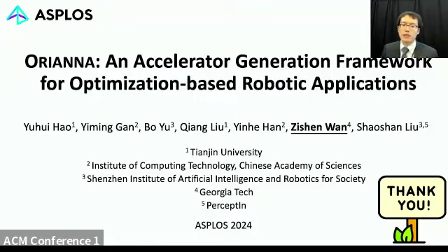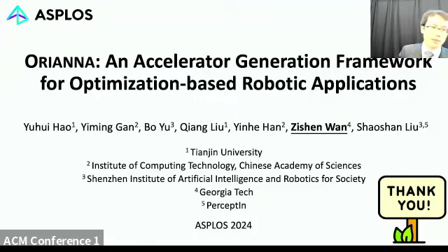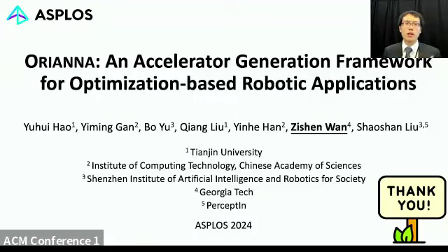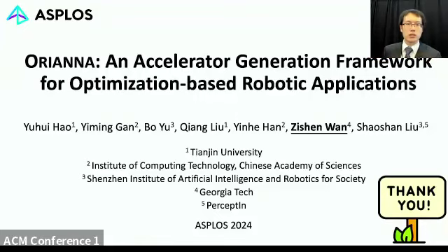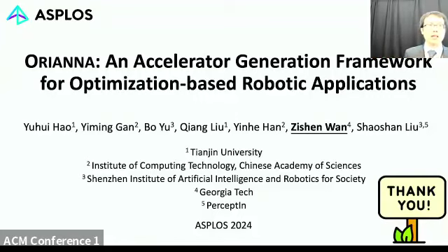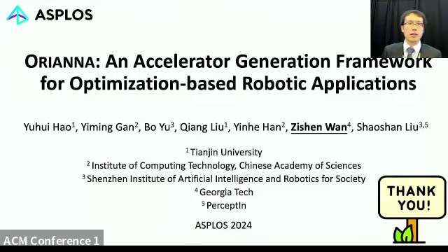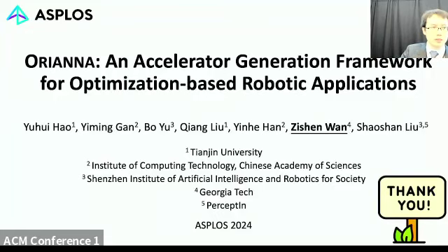Yeah, so the power constraint, I would say, comes from two fields. One is the robot field, say if you have a drone and it's battery supported, then the battery itself will have the power constraint. And second is a hardware constraint. So if we want to build hardware within this 1 volt or like that. Yeah, so we consider this power constraint and add it to the analytical optimization problem, so we can solve these problems to determine how many compute units we can have under this power constraint.